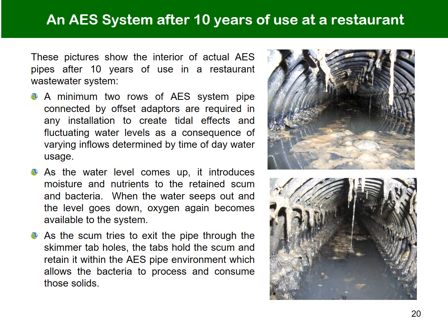These pictures show the interior of actual AES pipes after 10 years of use in a restaurant wastewater system. As the scum tries to exit the pipe through the skimmer tab holes, the tabs hold the scum and retain it within the AES pipe environment, which allows the bacteria to process and consume those solids.